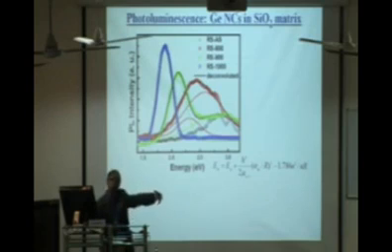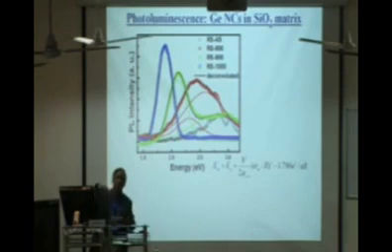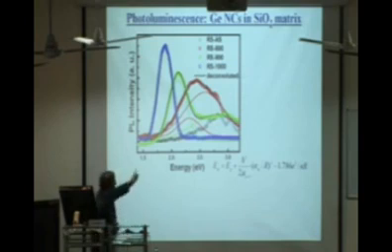In MBE grown quantum dots, we could see it only up to 50K or 40K, or after making a periodic array, up to 200K. But since the confinement potential is very strong, because silicon dioxide has a band gap of about 9 electron volt and germanium has a band gap of about 0.7 electron volt, they have a very strong confining potential. That gives rise to luminescence at room temperature.